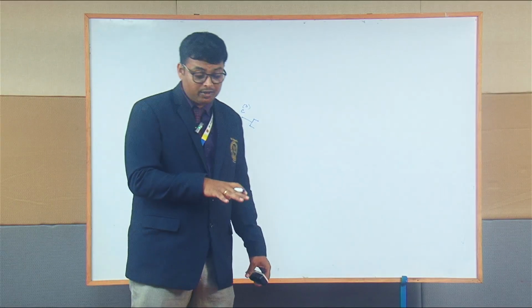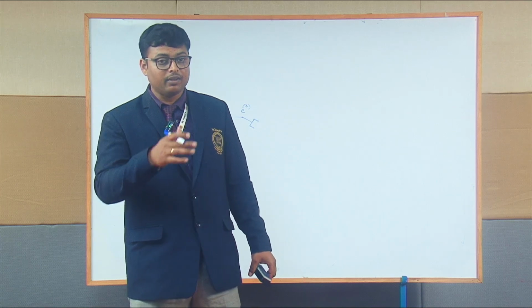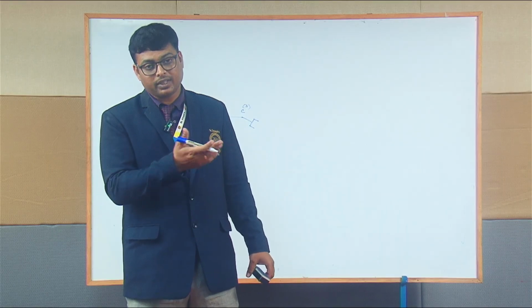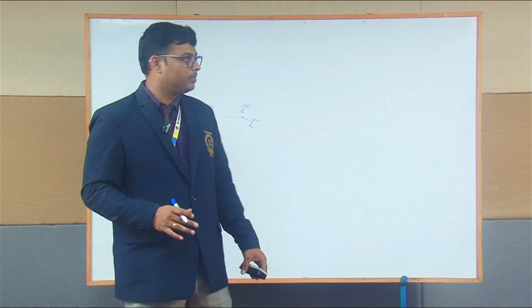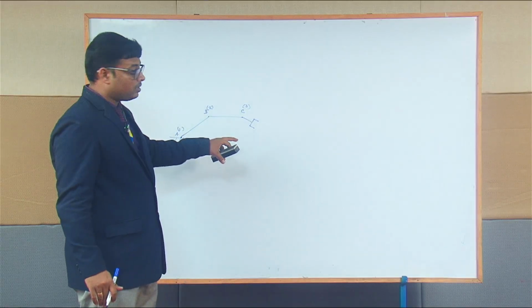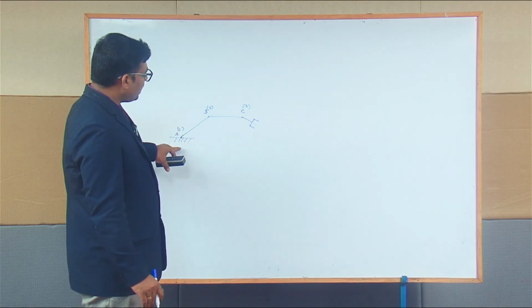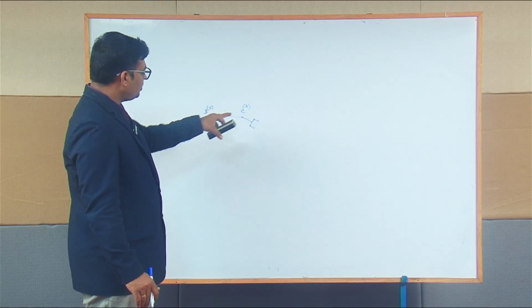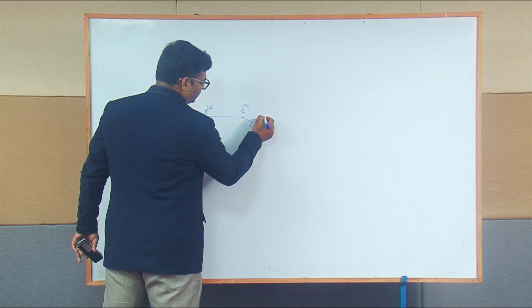We talk with respect to fundamentals. We may have many degrees of freedom. Again, I'm saying it is not restricted to only 3 degrees. When we include the wrist configuration, we have higher degrees of freedom, maybe up to 6. Any industrial robot nowadays will have at least 6 degrees of freedom, so 6 independent movements. So for understanding, we have an example diagram which contains 3 joints A, B and C, followed by an end effector.